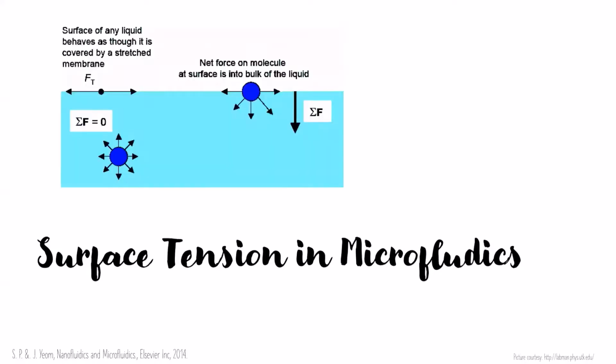A molecule in the bulk liquid experiences cohesive forces with other molecules in all directions, leading to a net zero force. A molecule at the surface, however, experiences only a net inward cohesive force. The difference in the cohesive energy over a surface area is represented by surface tension. If you pause to ponder what the units are, you'll realize that since it's energy over area, the units are joules per meter square, or simply Newton per meter, suggesting the behavior of surface tension as a force.